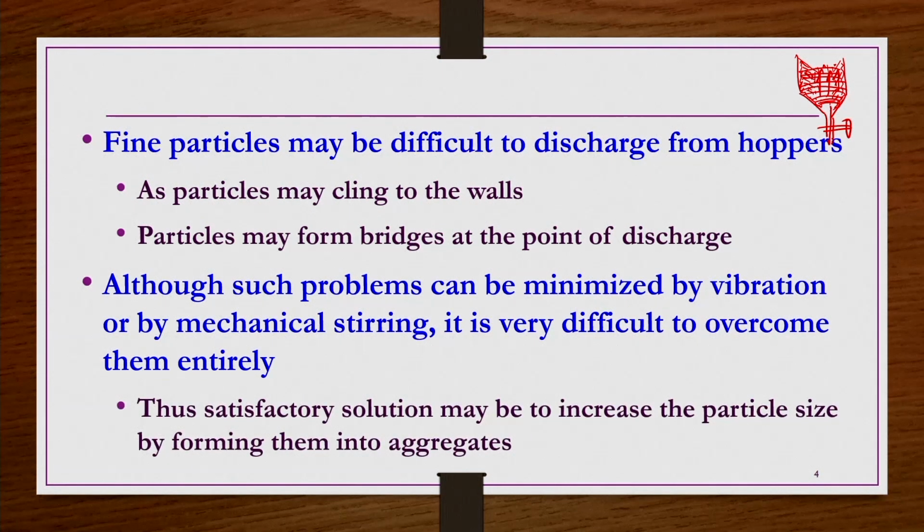Because of that, it is always possible to have a solution, maybe to increase the particle size by forming them into aggregates. That is the best possible solution, or if not the best, a satisfactory solution, where you can conveniently make solid particles move or flow. If it is not the best option, it is a satisfactory option. So, increasing the particle size by size enlargement methods is going to be very useful.